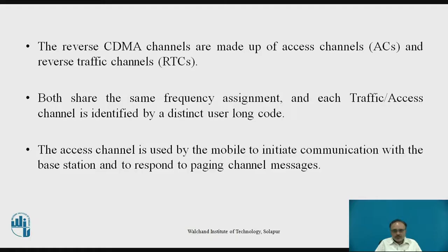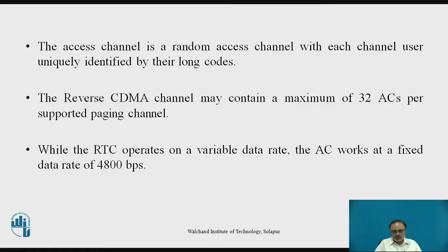The reverse CDMA channels, as we have seen in the last PPT, are made up of access channels as well as reverse traffic channels. Both share the same frequency assignment, and each traffic or access channel is identified by a long code. The access channel is used by the mobile to initiate the communication with the base station and to respond to the paging channel messages in a random process, with each channel user uniquely identified by that long code.